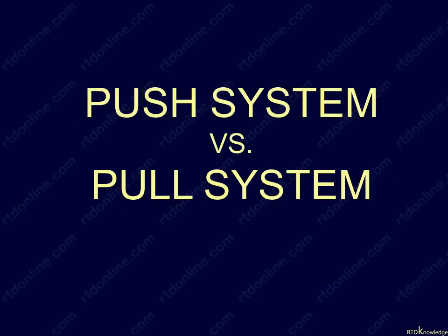Nowadays, you may also hear about push and pull systems. These are nothing but fancy, easy-to-remember labels for our make-to-stock and make-to-order systems. The make-to-stock is the push system since all prior processes and workstations, including suppliers, tend to overproduce and push their outputs to the next process. Every process seems to be pushing inventory down the supply chain, producing according to its capacity, mindless of the takt time or take-up rate of the next process.